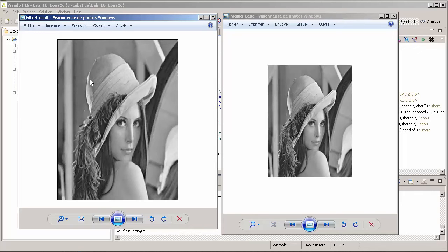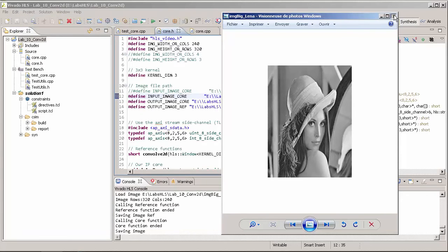So the first pixels that you put into the line buffer will not come out until after a certain delay, and this delay is basically 2 lines plus 3 elements in the case of the 3x3 kernel. So the first thing that we need to solve is this. We want to avoid having this shift. So how do we solve this?